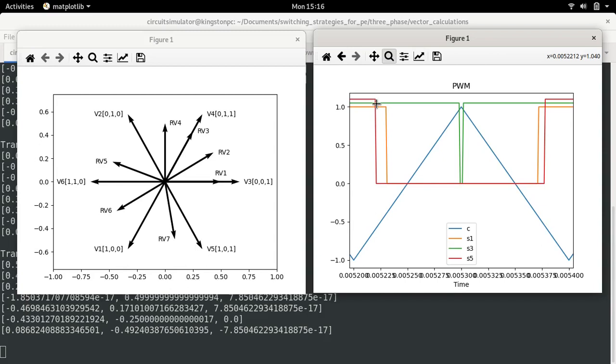All right. Now, what are the inferences we can draw from all this? There are several inferences. We are doing basic PWM, right? Now, in basic PWM, we were actually giving 3 different modulation signals to 3 different converter legs, performing sine triangle modulation, getting our gating signals. But really speaking, it appears as if we are actually applying the converter voltages also. We are indeed applying the converter voltage, except that we are not directly applying them. We are applying them indirectly. We are generating the gating signals and then we are inferring which are the converter voltages which are being applied,